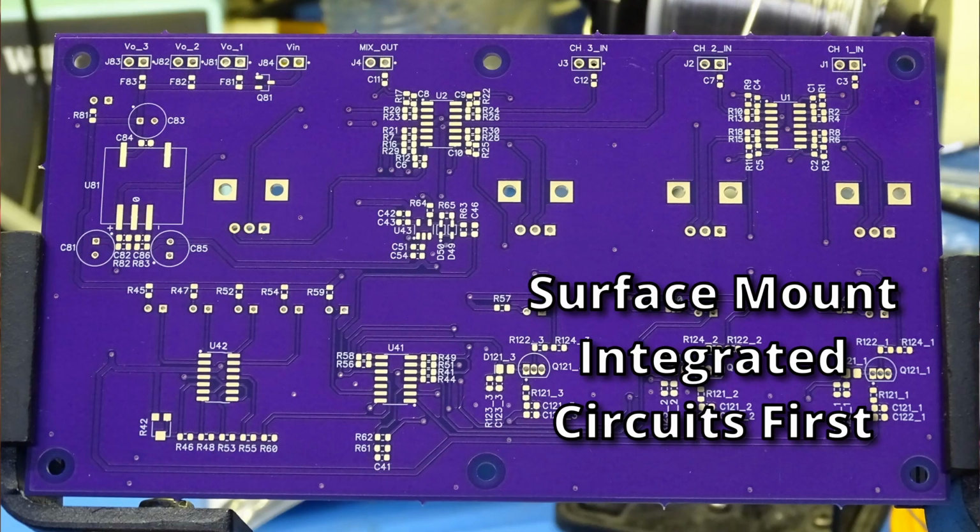I always start with the surface mount integrated circuits and transistors. In our case, we have that DC to DC converter, which is sort of integrated circuit-ish, kind of, sort of, but it's tall, and its tallness could get in the way of placing other parts. So this is not included in this initial placement.